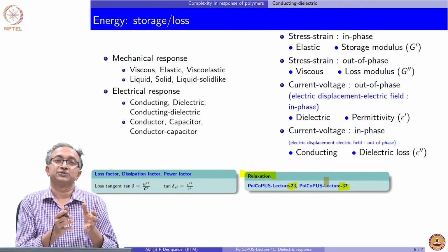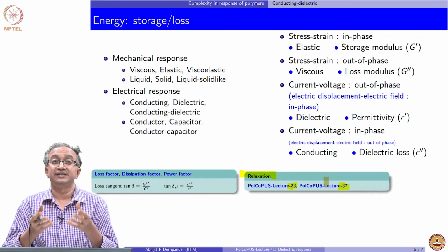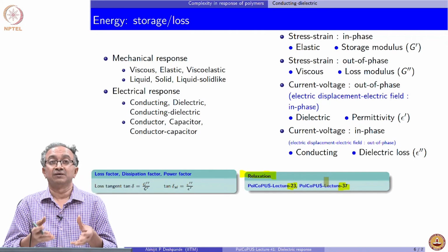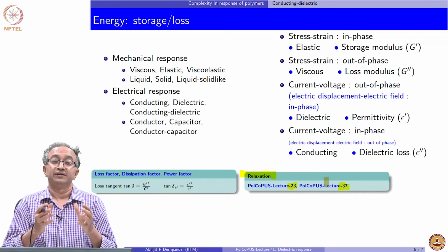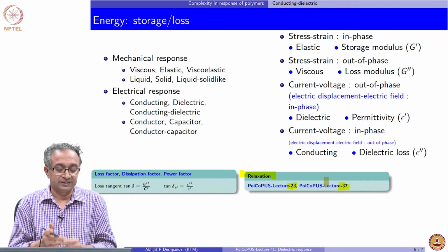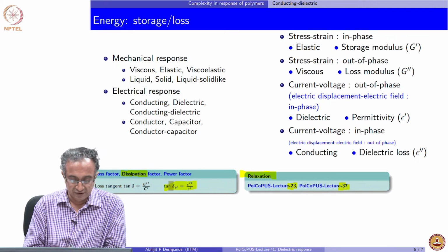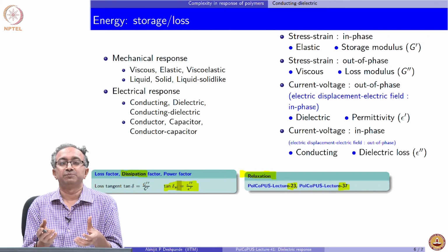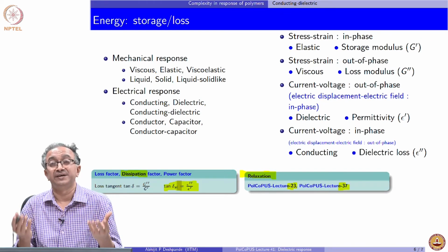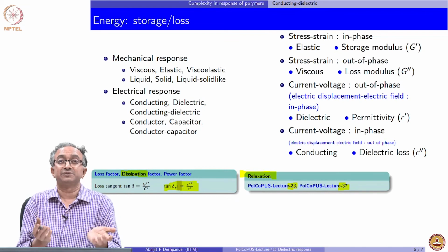Relaxation phenomena, whether associated with a segment moving or a macromolecule moving, are liquid-like molecular motions which lead to dissipation in polymeric materials. So, understanding relaxation is central to understanding how dissipative a material is, or how much dielectric loss there is. If segmental motion is possible, we have the possibility of loss. If segmental mobility is too high, dissipation will again be less. If segmental mobility is not there and the material is frozen, dissipation is again not there.